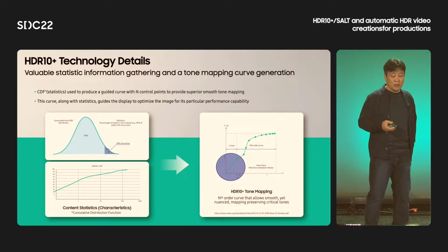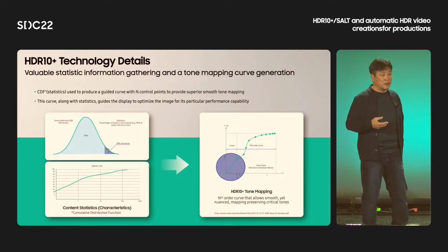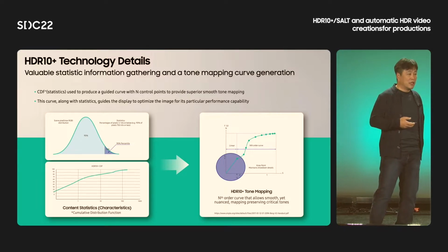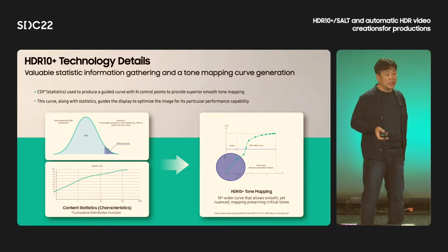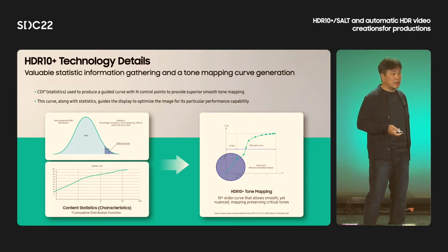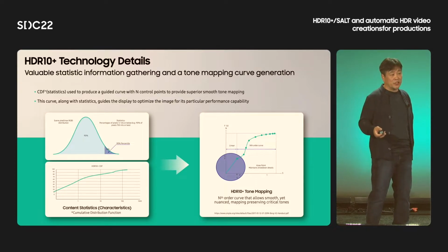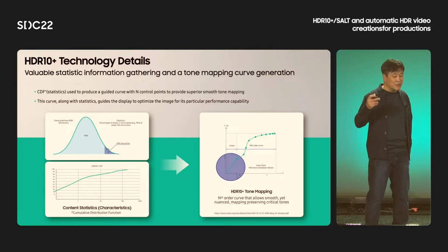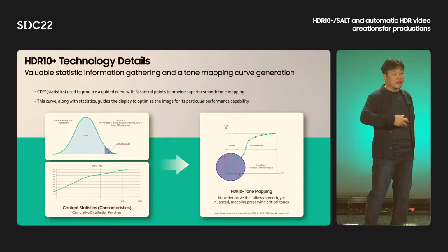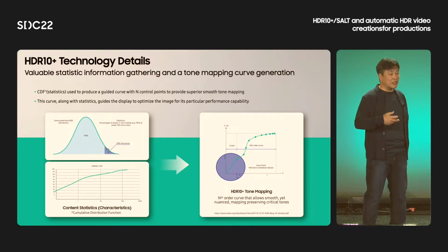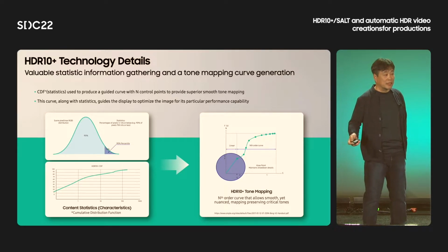If you had a chance to look at the SMPTE 2094-40 standard or the HDR10 LLC spec, maybe you can get a more detailed idea of how we get that creator intent preservation. The concept is conceptually very simple: collecting statistical information and migrating that characteristic to the tone mapping process, to make the best mapping curve. That is the concept.